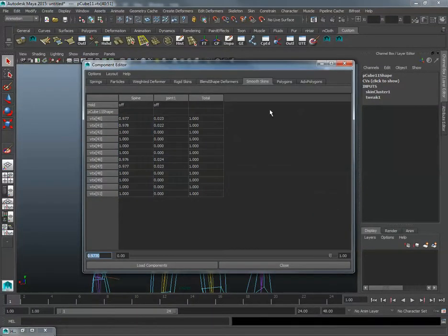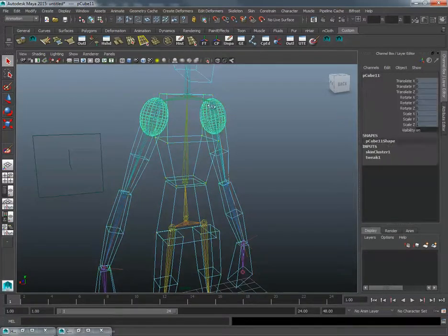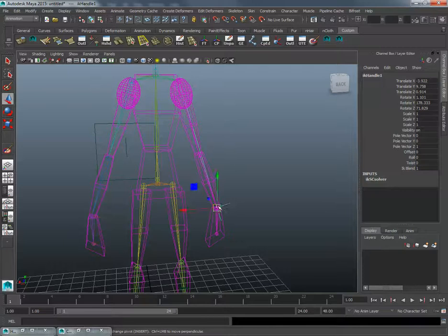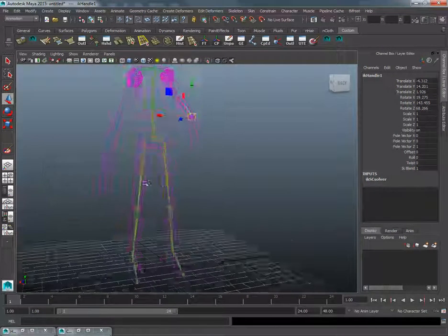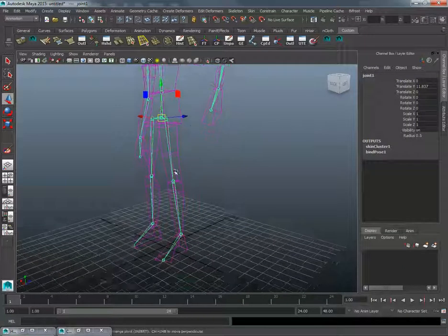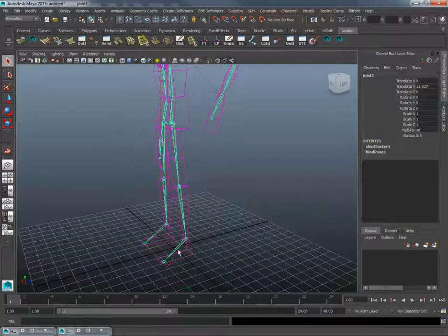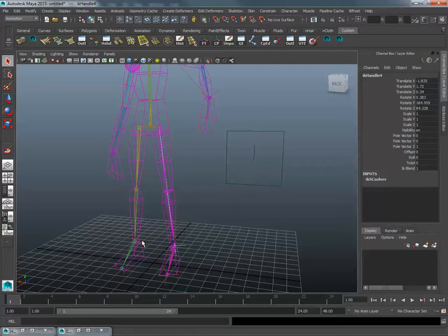It doesn't update automatically, so I'm just going to select all these like an Excel spreadsheet, press 1, and that'll give full control to the spine bone in there. And that means what should happen is when I grab a wrist and move it into place, now it's not affecting that bit. So now what I can do is I can grab, now these are all controlled by IK handles, these ones here.